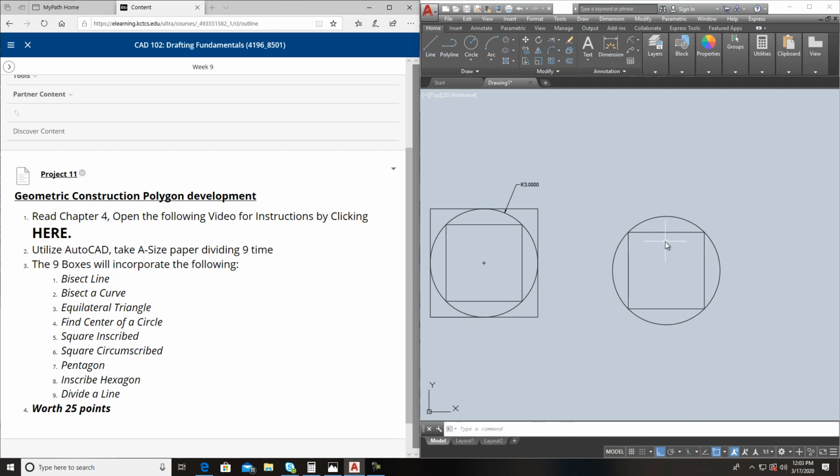That's the old method. This is the newer method. We'll go in there and do it again, and this time we're going to do circumscribed, and the radius is 3, and put it out just like that. So it's the same thing, you're just going about it in a little bit different ways. AutoCAD calculates for it, and over here you're doing it manually.